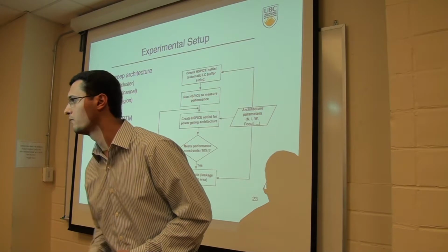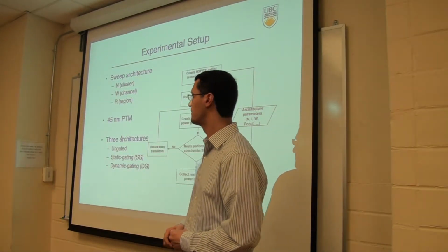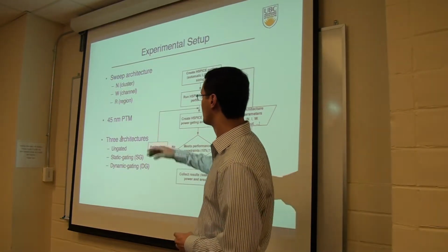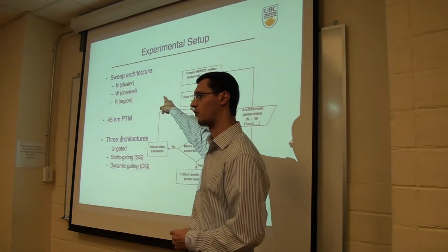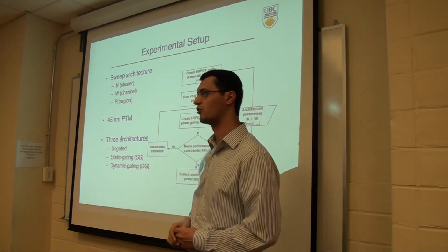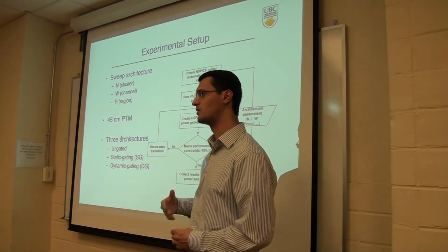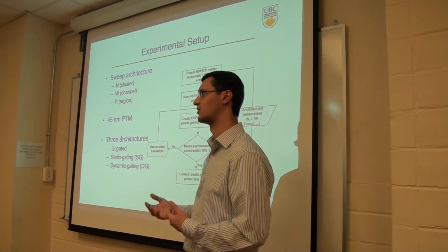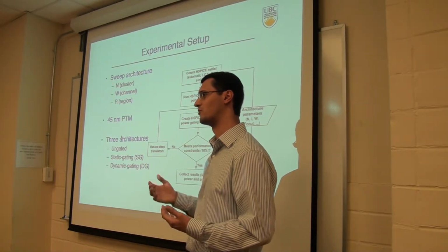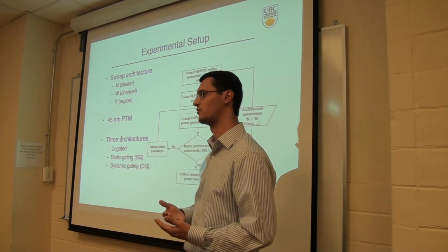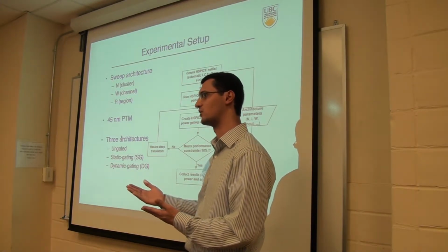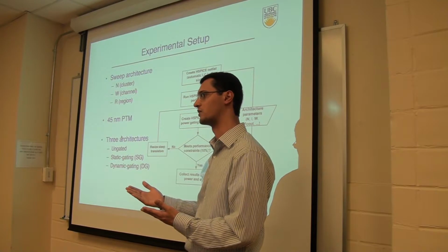Just a question. What did you mean in the top box there, automatic LC buffer sizing? Basically, because we are varying the architecture parameters, like the cluster size and the channel width, we did some buffer sizing using scripts. For example, if we increase the cluster size by X, we increase the buffering. We may add an additional stage in the buffers of the input pins.